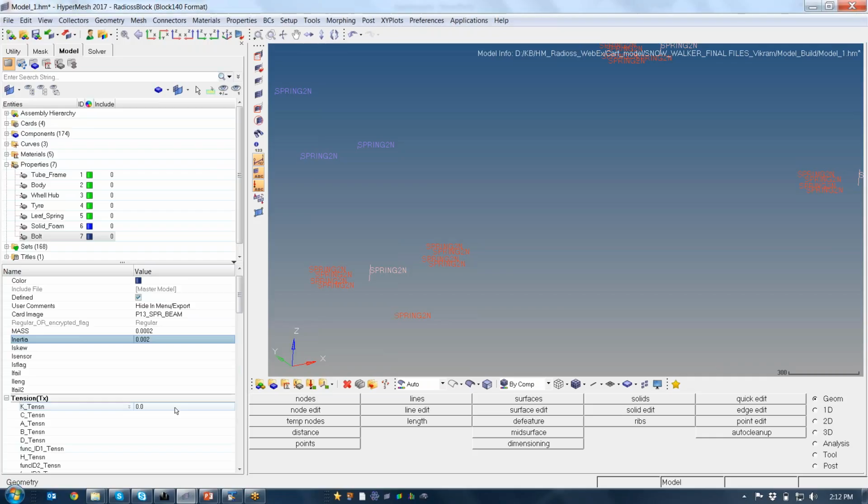This is a type 13 spring which follows the local coordinate system. Since it is a beam type spring, node 1 to node 2 is always x, which is tension. But here I'm making everything high stiffness. If you put this spring in the output request, you'll get to know how much axial, shear or bending load is coming into these springs.